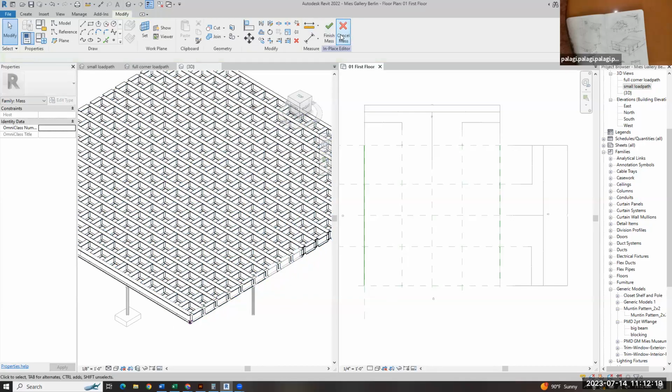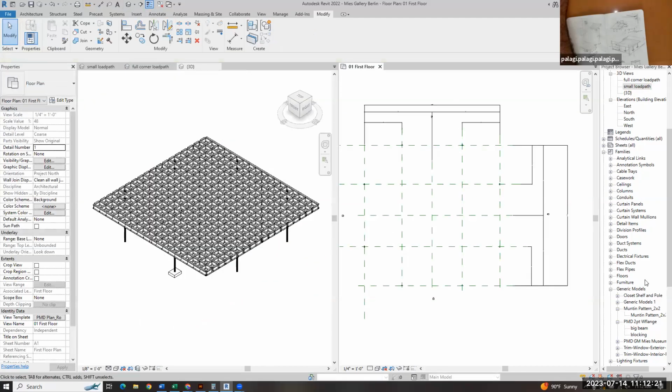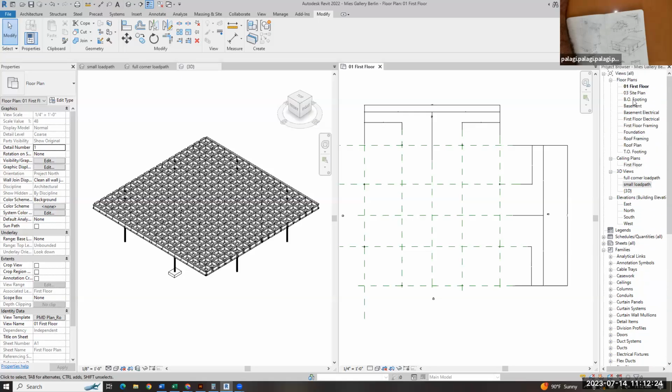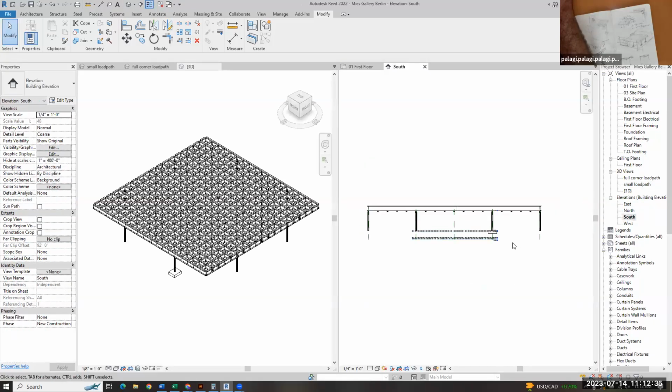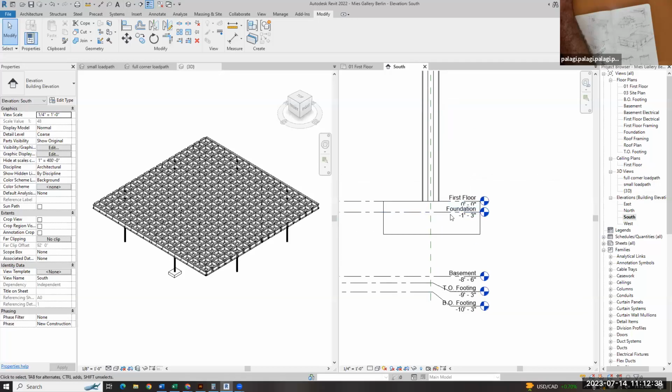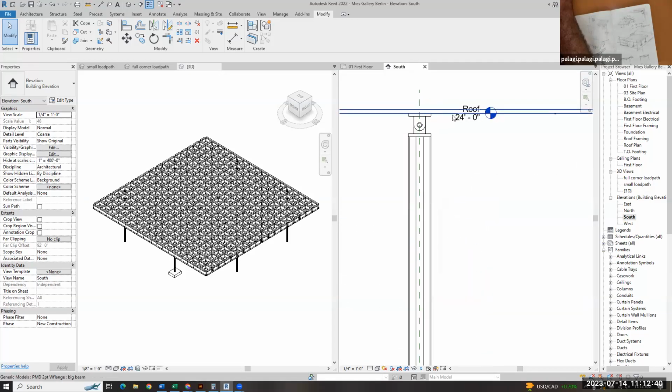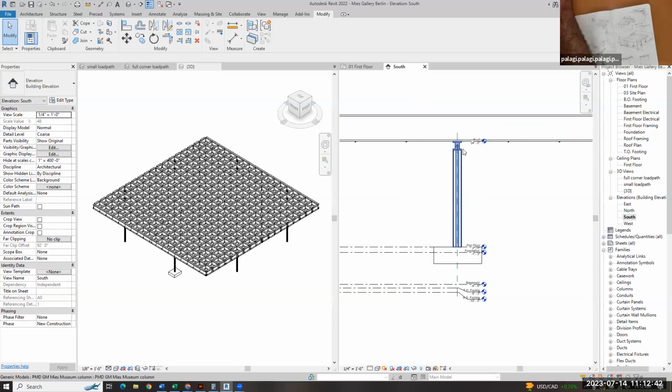What was nice then is that that was set. We're talking about heights. The reason it's nice to do the entire finished thing in the project instead of the conceptual mass world is that we can set the elevations to work with the correct levels. So I have first floor and roof elevations tagged. I'm actually working with the real levels, which means all of our views and sheets work. If you just bring in this big object from conceptual mass, it's not locking to those same things. So that was kind of a nice thing.